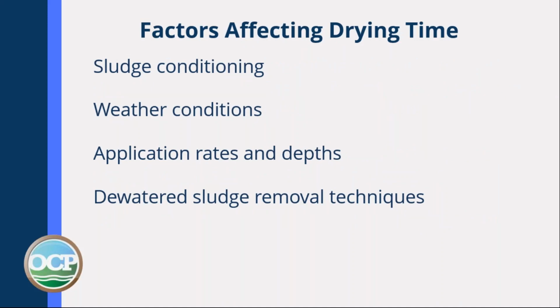Factors affecting drying time: sludge conditioning, whether you use polymers or not, and the weather conditions. You can imagine in the winter and in the wet season, it's going to take a lot longer to dry sludge. I've seen some drying beds in parts of the state that they now cover to help them use them year round.